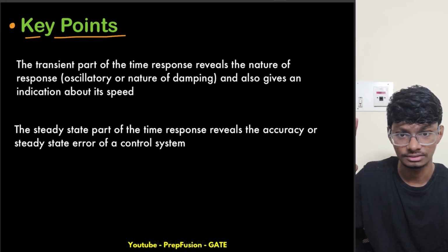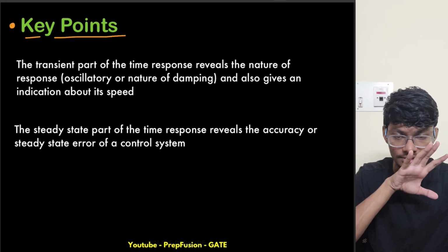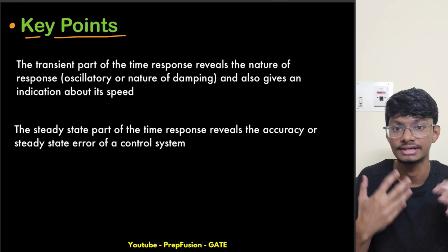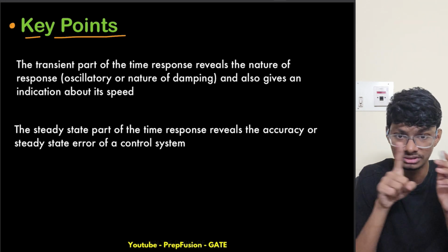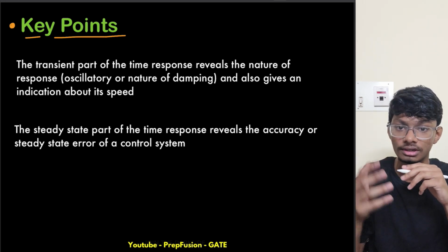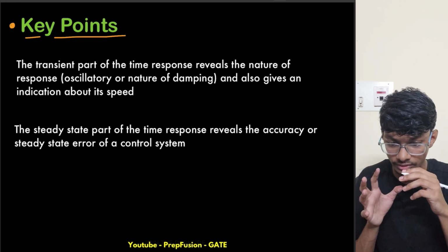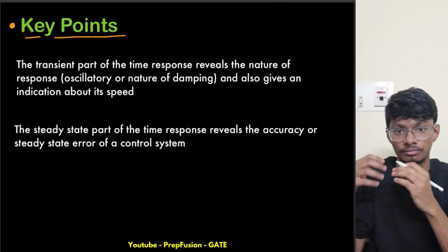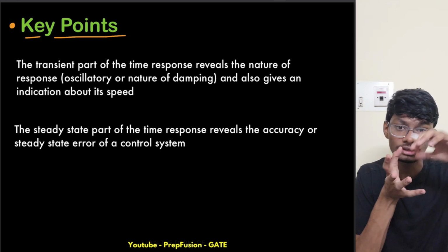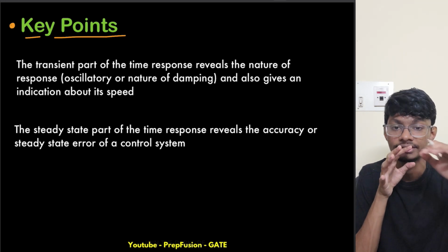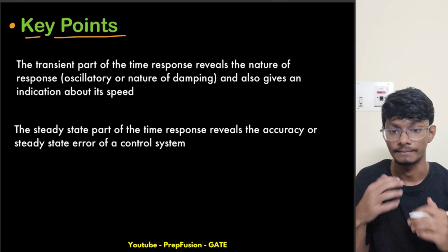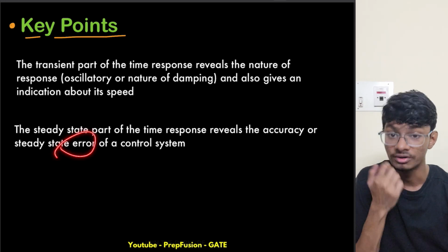Basically there is a sensor that will measure the room temperature and also the desired temperature that you want. It will measure the difference and give it as input to the controller. The controller will do some mathematical calculations and give it to the actual AC input, deciding how much cold air it needs to give out. All those calculations will happen in the system. So what is the error in this case?